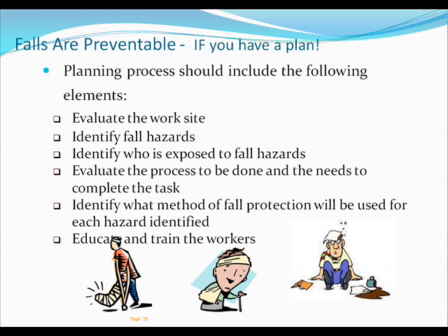One of the most important aspects of fall hazard prevention is planning. An assessment of all fall hazards, even potential fall hazards, must be done before the appropriate corrective measures are considered. Furthermore, a fall hazard assessment can also determine training needs and fall rescue methods.